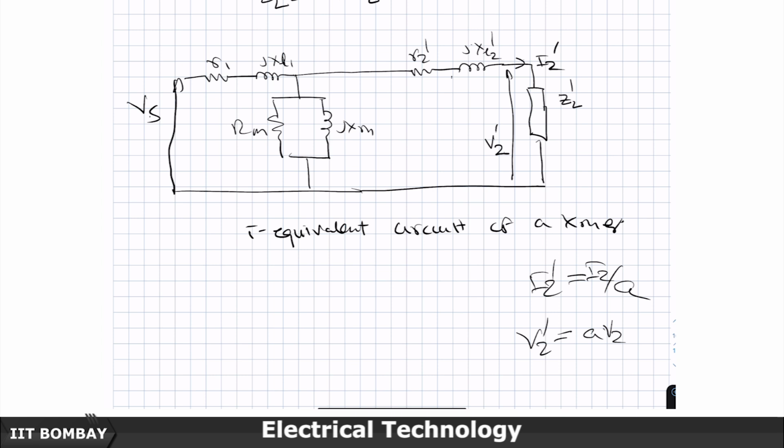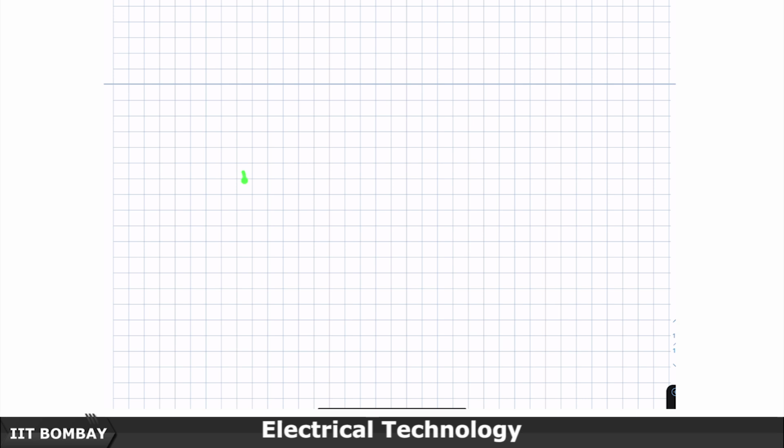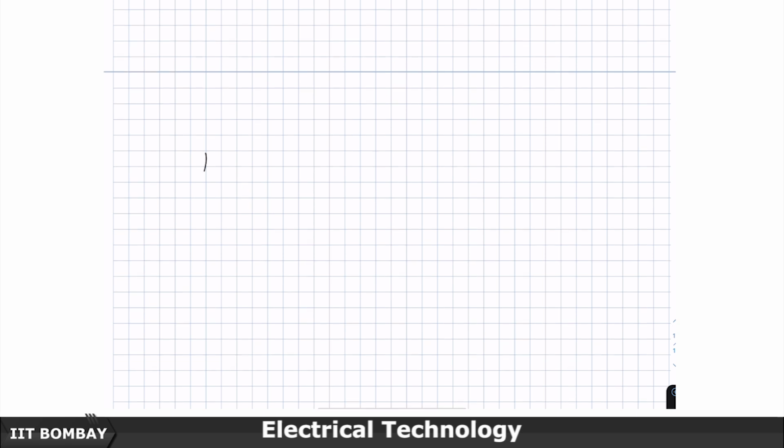You can work with this, there is no problem with it, but these values are in practice relatively very small, and this value is usually very large. So, if this is 100 amperes and this is 1 to 2 amperes, for most of my calculations I can take this outside, ignore it and do a calculation as if the circuit is simpler. This is engineering now, the engineering approximations.